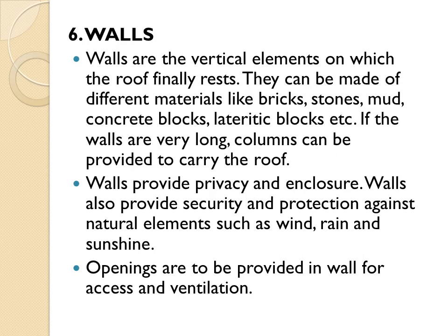So the next important part of the superstructure is walls. Now walls are all the vertical elements which are constructed with various materials such as bricks, stone, concrete blocks, laterite blocks, etc. The material can be of any type. If the walls are very long, columns can be provided to carry the roof.